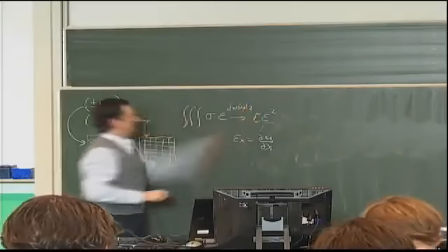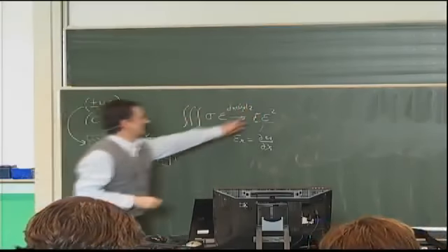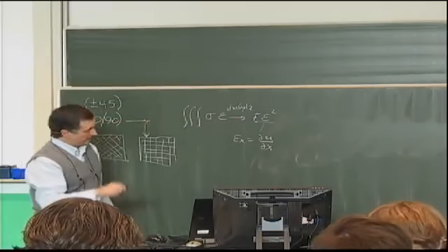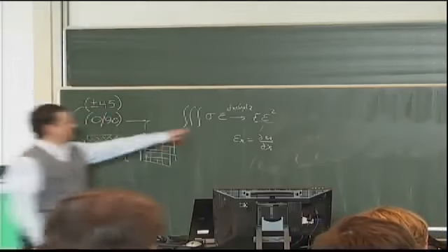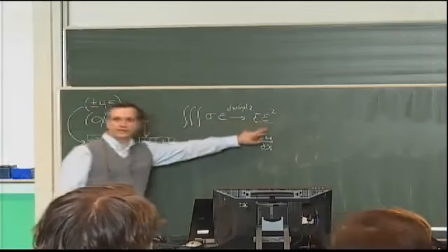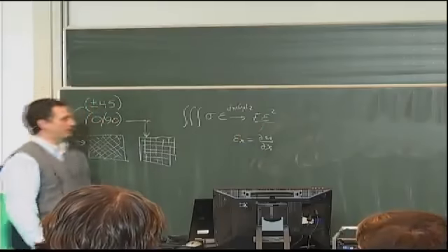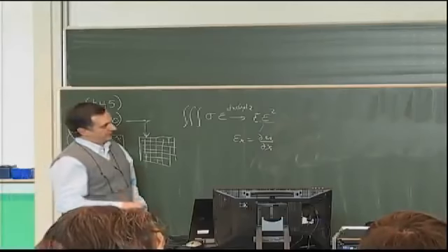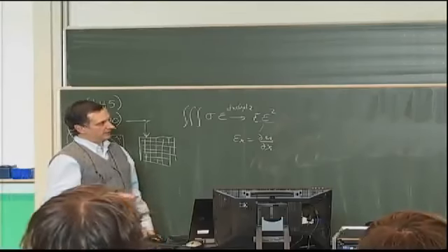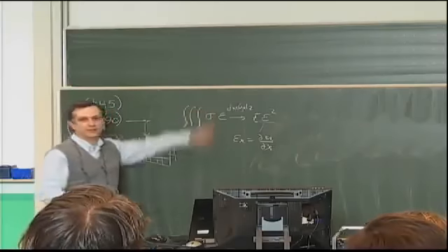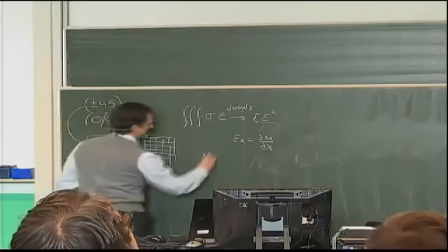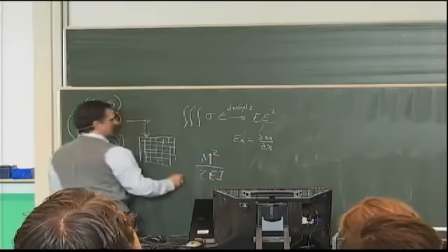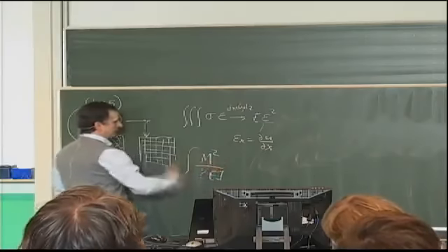So if one of these has already been eliminated, then instead of having E involved in the integrand, I will have the A matrix. So this top line involves the terms that we would consistently know to find in a plate problem in isotropic material in a membrane kind of situation. The very bottom one, which involves now the curvatures, has an equivalent to this kind of derivation that usually we know in terms of M squared over 2EI if it's a beam. And again, this is integrated over the length of the beam.